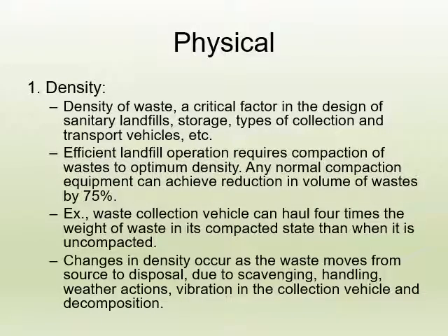So first, the physical property or characteristic is density. Density of waste is a critical factor in the design of a sanitary landfill, storage containers, and storage facilities, and in the type of collection, meaning the volume of collection vehicles and transport vehicles. Efficient landfill operation requires compaction of waste to optimum density.